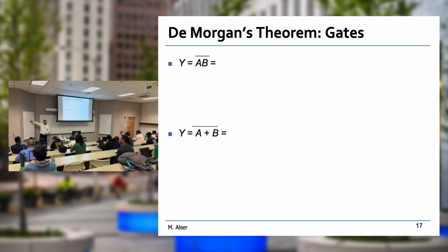You really need to go through this. You decide where are the two sides in my equation. Remember, if there are parentheses, then each parenthesis term is really a single term. That's one side. You cannot split it in half. You take it as one side, everything else is another side, and then you flip the sign from multiplication to OR, or from OR to multiplication, and then you distribute the bar at the top over the two sides that you decided. Not over the variables, but over the two sides. If this has a C multiplied with B, so this bar will be over B and C together. Okay, and then you continue until you get no more large bar at the top of the variables.